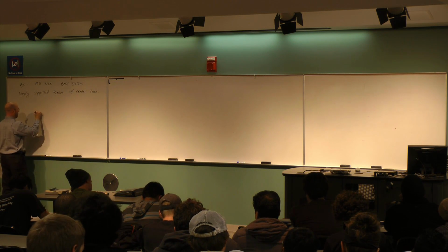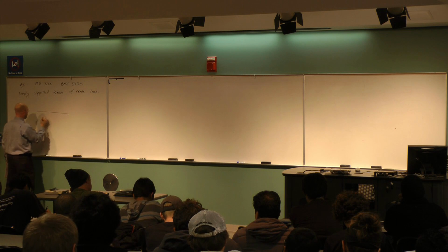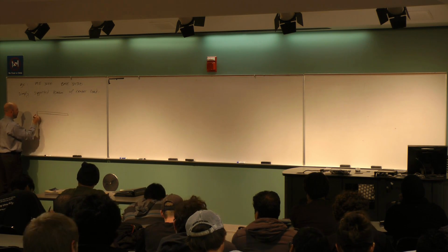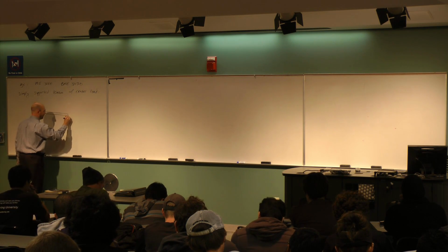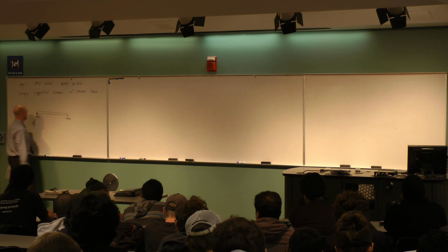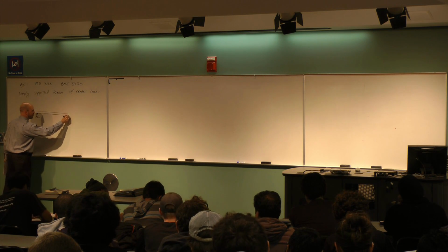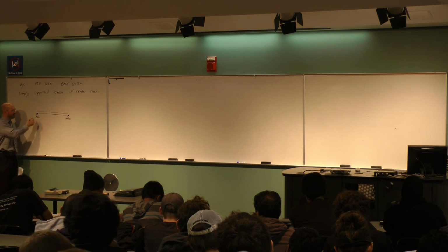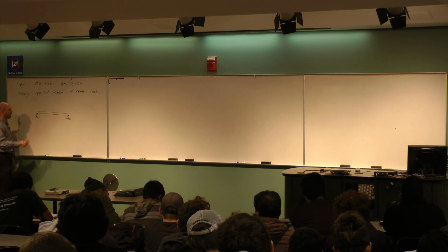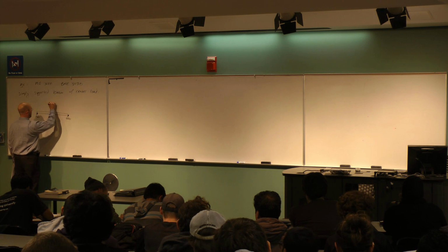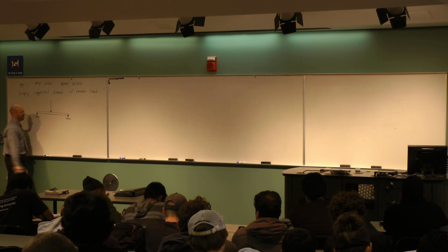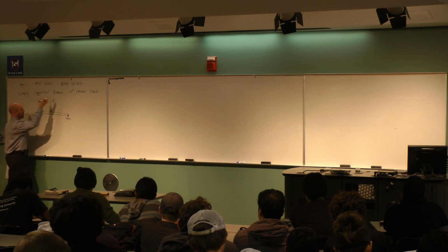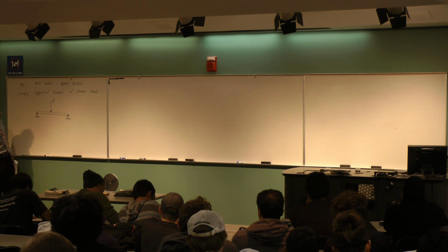Okay, and so what does this mean? Simply supported for a beam basically means that the ends are pinned. Here's what I mean by a pinned end. I've got essentially hinges at the ends so that if this beam wants to deform in some way, it is free to rotate at the two ends. And if I put a load right in the middle of a beam, the nice thing about these beam problems is they're pretty intuitive, even if you're not a mechanical or biomedical engineer, you're an electrical engineer.